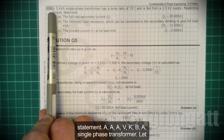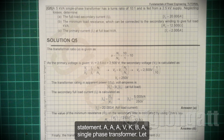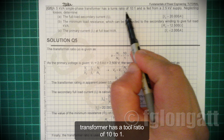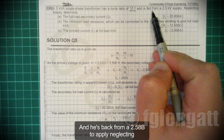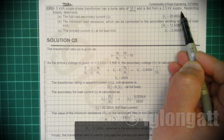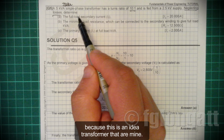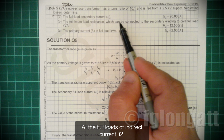A 5 kVA single phase transformer. Let me put here the notation. This is an ideal single phase transformer. It has a turn ratio of 10:1 and is fed from a 2.5 kV supply. Neglecting the losses, of course we are neglecting the losses because this is an ideal transformer. Determine A, the full load secondary current, I2.